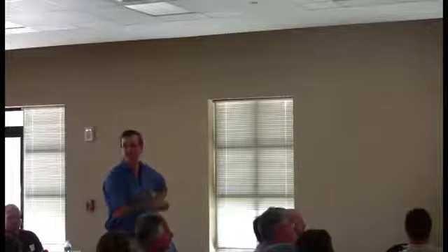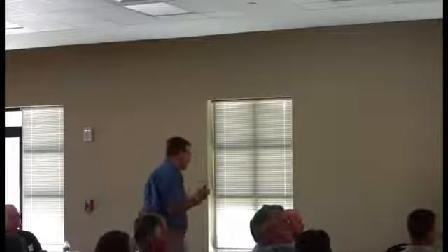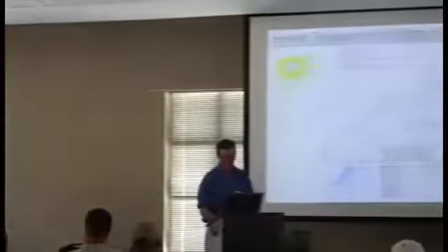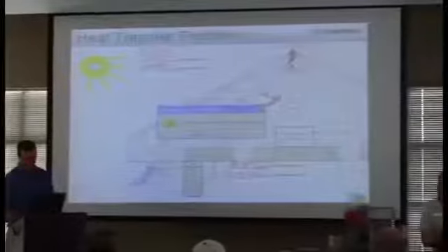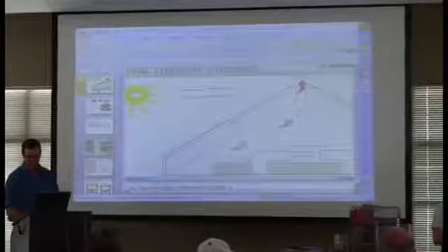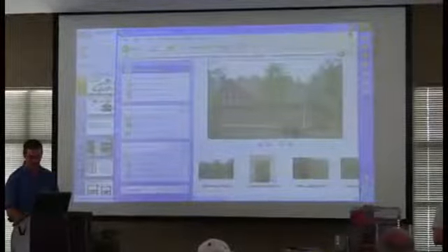If I have foamed the roof line and the ducts are located inside the building envelope, do I have to insulate them via the energy code? And Roxanne, what's the answer? Because they're in conditioned space, you are not required to insulate them. It's kind of crazy. However, I'm going to say in the same breath, although it's not required, it is highly suggested. Why might that be?